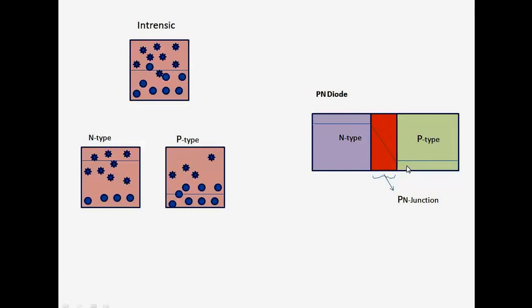In a material, let us suppose an n-type material, if we want to pump an electron from the valence band to the conduction band, we need to supply some energy. Then where do we get that energy? For an ordinary diode, we have to give that energy from some external source. Whereas in a PN junction, in a photodiode, in a photovoltaic cell, that energy comes from the incoming photon radiation.